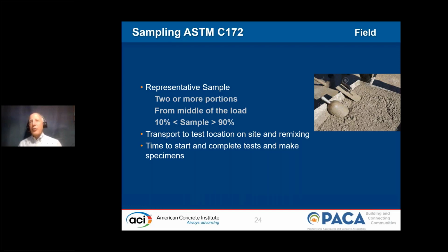How many times have you been on a job site where a mixer truck pulls in, the technician comes to the back, grabs a wheelbarrow, first thing off, he goes one way to do his test, and the concrete truck goes the other way to do the concrete placement? Well, that's not proper sampling, although we see it very often.